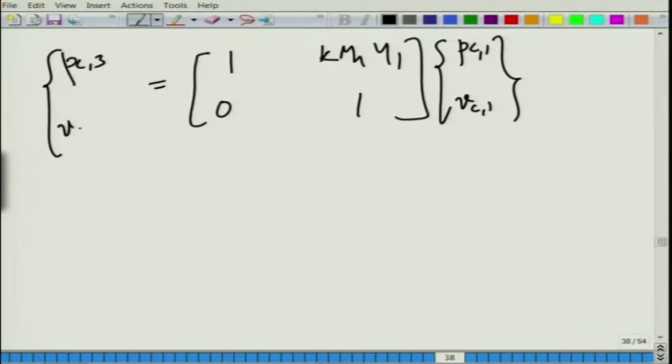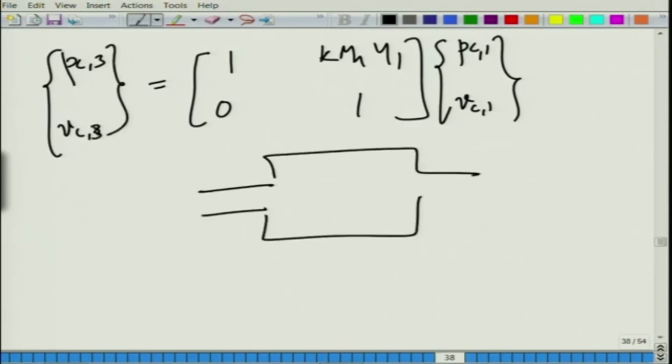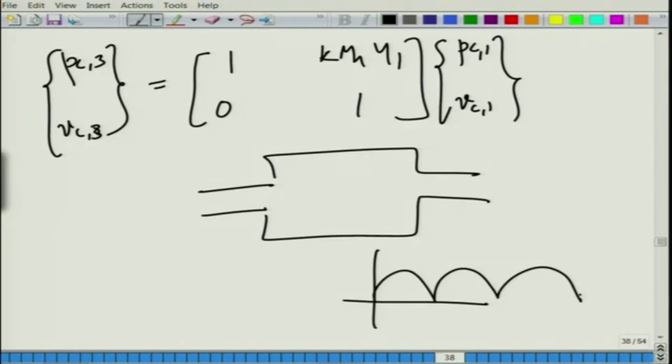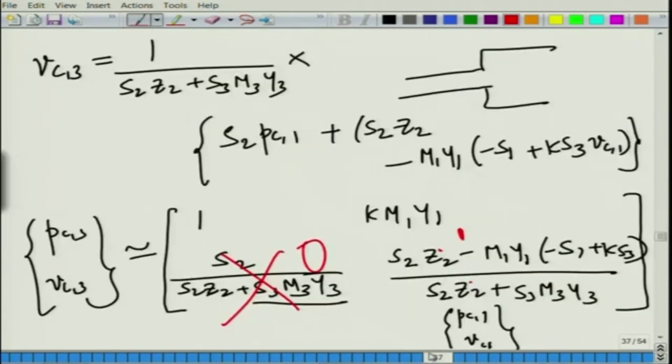incorporating the loss factor. So, this loss factor will actually do something for a simple expansion chamber. Incidentally, the loss factor for sudden contraction would be different from that of a sudden expansion, but whatever it is, this kind of transmission loss you are getting for a case of zero mean flow. So, in case of non-zero mean flow, these troughs will be slightly lifted, based on theoretical predictions, and these peaks will be slightly lower, this attenuation domes, but these are all theoretical things. Experimentally, pretty much the same thing will happen for this.